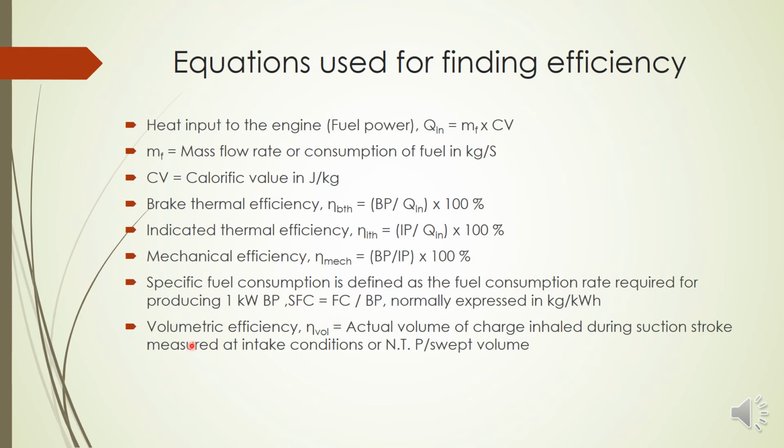And finally we have volumetric efficiency, another efficiency, defined as the ratio of actual volume of charge. By charge we mean the air-fuel mixture or the air only. In a diesel engine it is the air only, in a petrol engine it is the air-fuel mixture. So the actual volume of charge inhaled during the suction stroke, measured at intake conditions or normal temperature and pressure, to the swept volume. So it is the ratio of how much volume of air or charge is coming during the suction stroke to the swept volume.